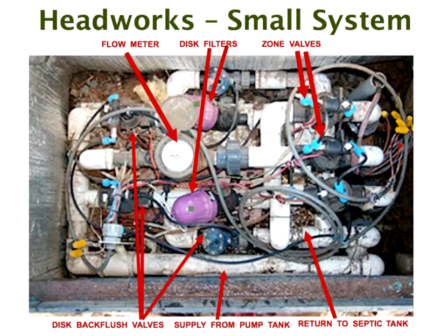Take them apart. This purple head will screw off and you can pull the discs out, clean them, and put them back in again. And here you've got your solenoid valves. Again, these should be taken apart to make sure that there's no debris under the diaphragms.